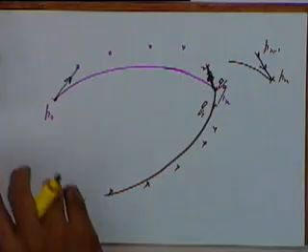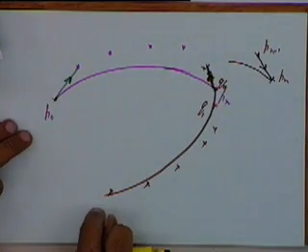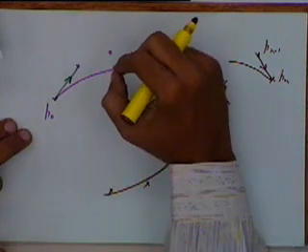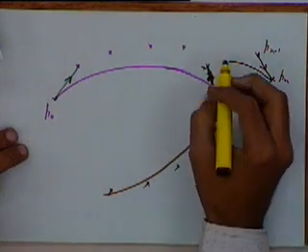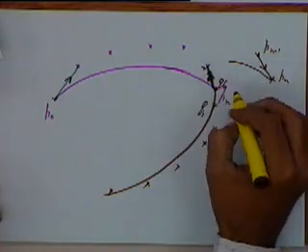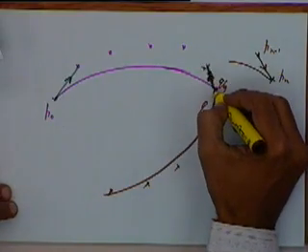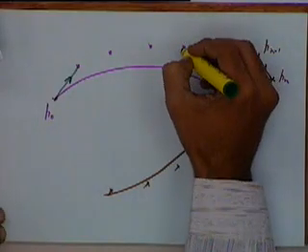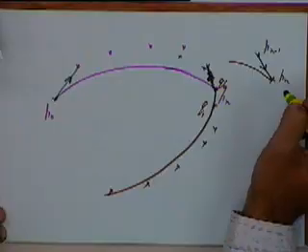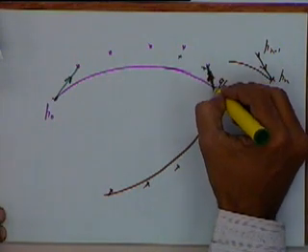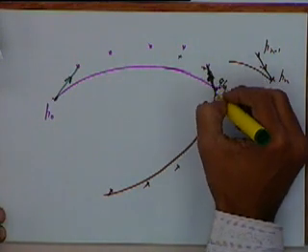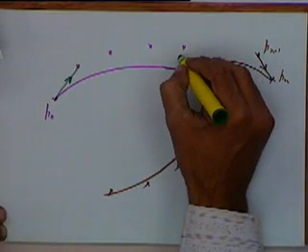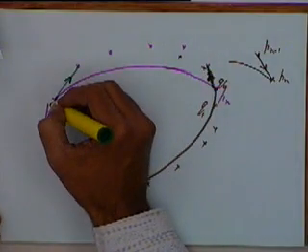The basic idea is that if I have a curve which I am using in any application, I want to have as much flexibility in modifying the curve as possible. So at this point, the tangent is in this direction. If I change this point, let's say from here to here, the slope at this point will still remain the same. So if I have two curves and I have C1 continuity, that continuity does not get disturbed by changing this point or any of the other points.